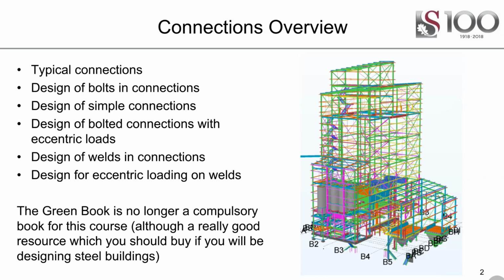An assembly is, for instance, a column with cleats and base plates and various things welded onto it. You will then send the completed welded assembly to site, and then on site you erect the assembly and bolt it together. Because what happens is you typically shop weld, site bolt.